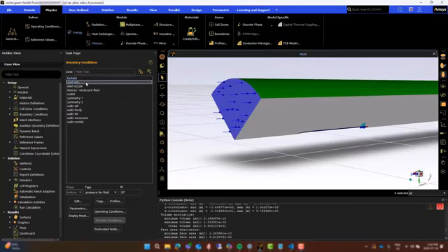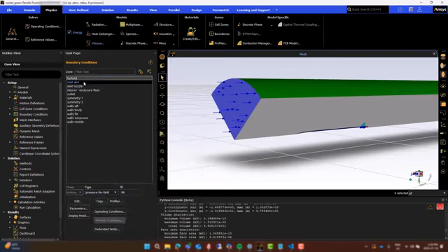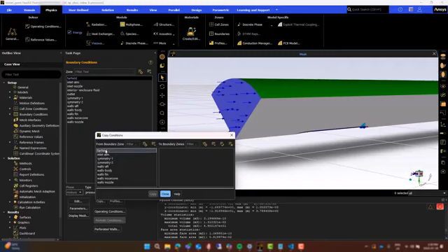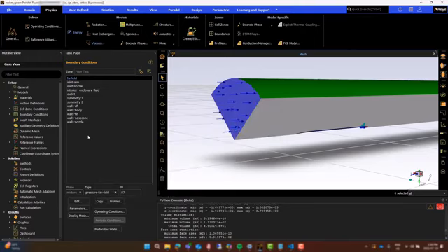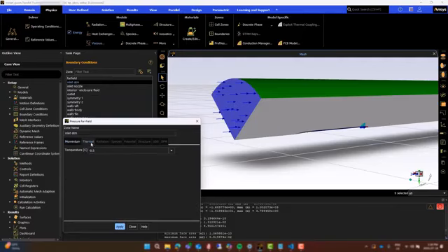Continuing to assign the appropriate boundary conditions for each surface, we'll notice that the inlet name selection was assigned a velocity inlet boundary type. We'll change that to pressure far field. And when you have multiple boundaries of the same type, instead of individually changing all of the inputs one by one, you can copy the inputs from a previous boundary and apply them to other boundaries of the same type. A double check of the boundary conditions for the inlet atmosphere showed they match the far field.